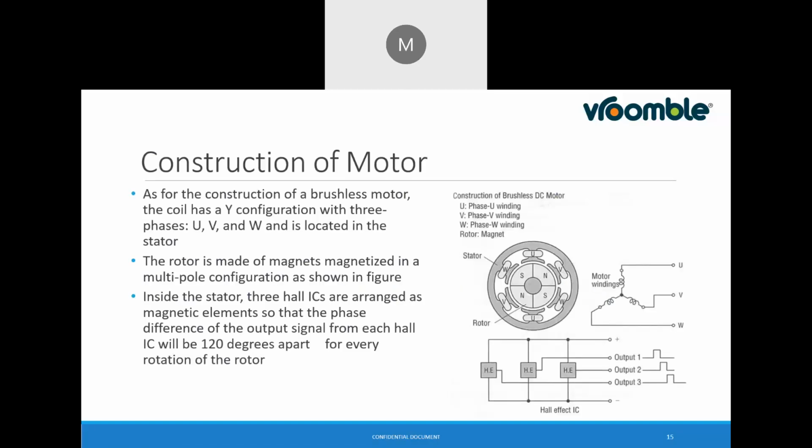At the same time, the BLDC motor will have the connections like UVW or delta configuration. The rotor will have magnets, like we have seen yesterday, skewed inside the rotor. There can be a different number of poles, 2 poles, 4 poles, and mainly an even number of poles.